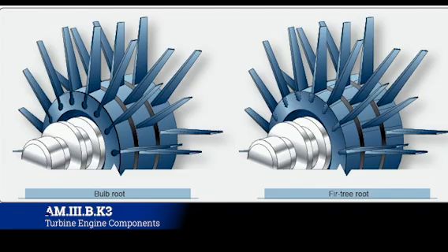And then the blade next to it might be 350 grams, and the one across from it is about 350 grams. All around the spinner, you'll find the blades with the most similar weights across from each other, and that's to keep it spinning as evenly as possible. If you get one that has like 400 grams on one side and 10 grams on the other side, it would shake it all to pieces. And with the RPMs and power that we're dealing with, it would absolutely just eat itself. So, in order to make it effective, that's what you have to do.